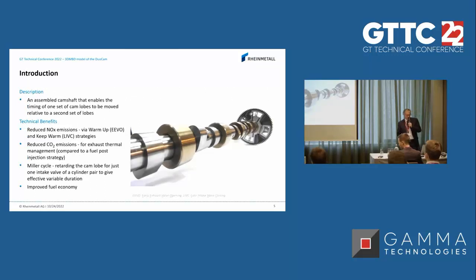The DuoCam is an assembled camshaft that enables the timing of one set of cam lobes to be moved relative to a second set of lobes. That means that the DuoCam is used to change the valve timing. This has certain advantages on the engine performance.